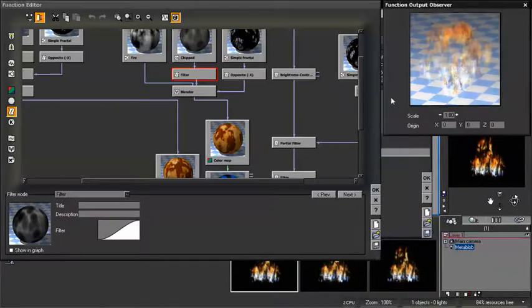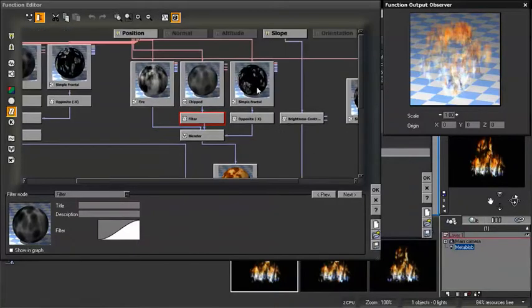And if we take a look at the preview, we can see that a little better. So instead of our flames changing from the color blue to orange, there's a nice separation, and they sort of mix in between each other. Because typically, before that blue changes to the orange in a typical flame, we have a lot of transparency where the flame almost becomes invisible. And this is a good way to reflect that.